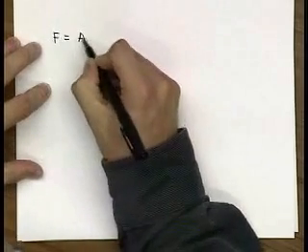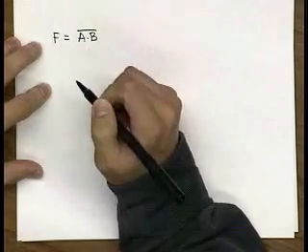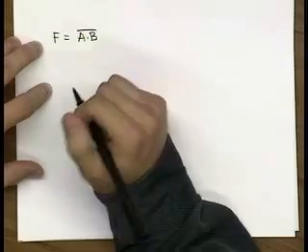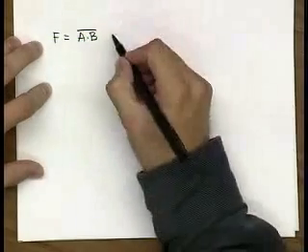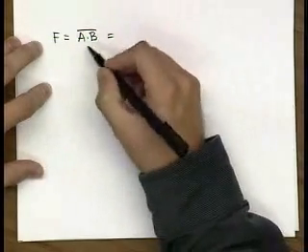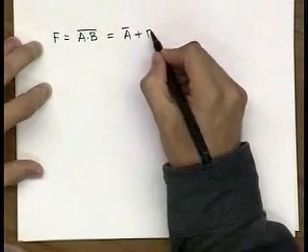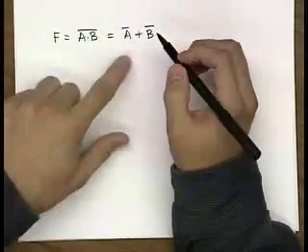So every time you have a function, for example a NAND gate, you have A, B. That is your pull-down. You always have this big bar on top to implement your complementary function. And then using the De Morgan theorem, you apply De Morgan principles all the way down to these simple terms that correspond to your signals.